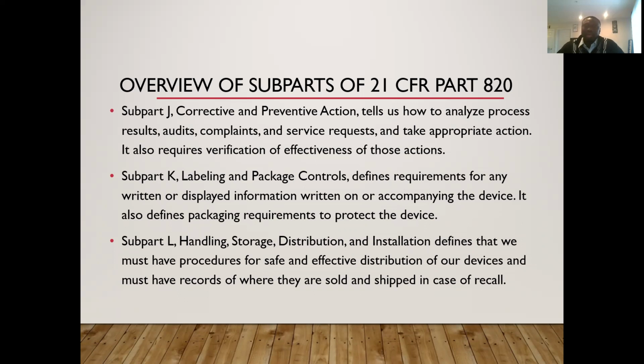For example, if a product coming in from a supplier has been going through a series of non-conformities every time, a CAPA can be created such that from a supplier perspective, we do a root cause investigation to make sure we eliminate that root cause. And if we eliminate the root cause, there's a time frame where we put in place, are we going to tighten the inspection that will check for these non-conformities, these failure modes? After we check for them and they are effective, then it becomes a standard operating procedure which the organization will be using at their incoming inspection. That's an example which I want to show you over here.